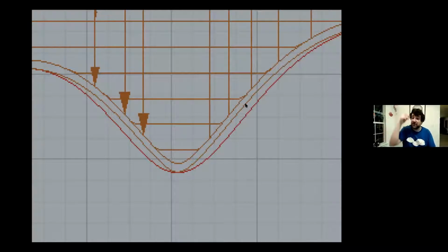And so I can then zero the machine. That's when I set up the origin of my axis. So the position that I'm going to consider for those three things that I have moving to be 0. I can move that until the tip of the tool touches the top of the surface. And the way that I generally set things up is to set that as the 0 height. So the top of my material is the 0 height. When I'm cutting, I'm always cutting in negative values. If I'm in positive values, I know I'm safe to move around. I'm not going to interact with the material.